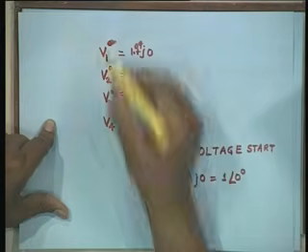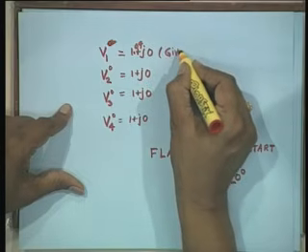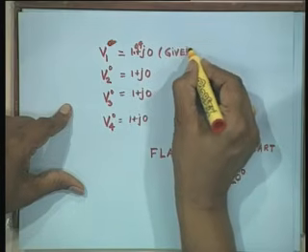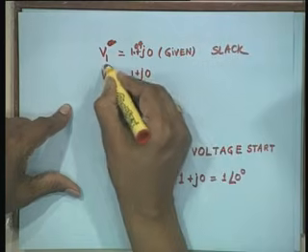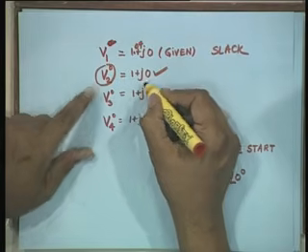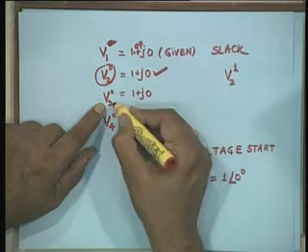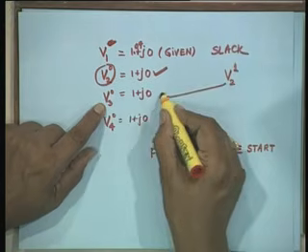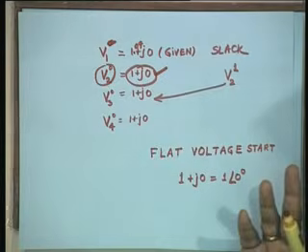So, there is no 0 here, it is given, because bus 1 is our slack. So, once you know V2(0), at the end of first iteration it becomes V2(1), and when you calculate V3(0), use this rather than using this old value. This is Gauss-Seidel.